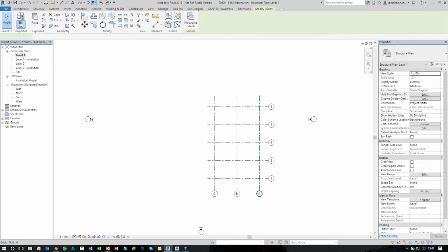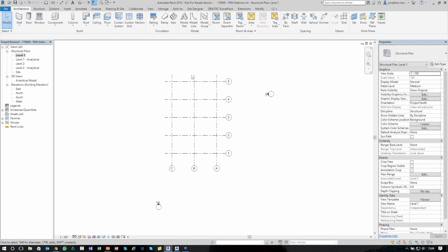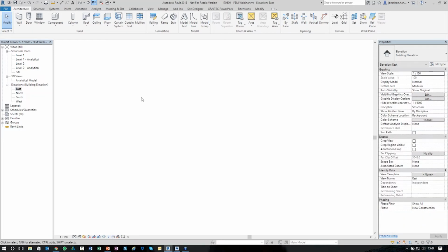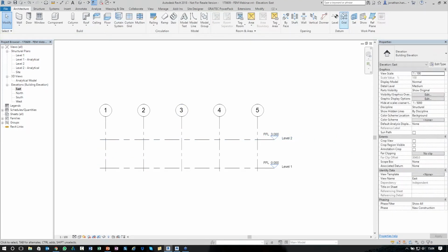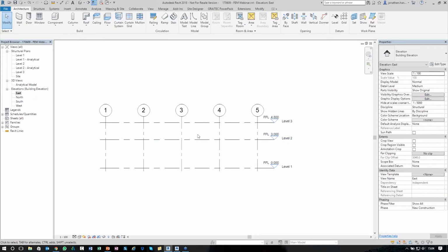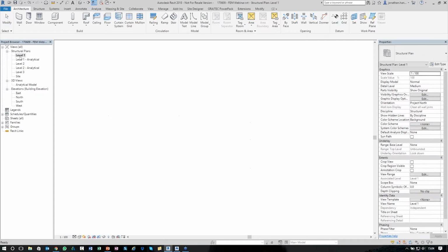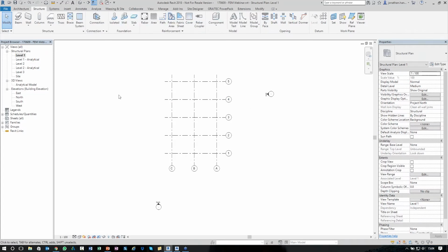I'm going to click into level 1 and start drafting a very simple structural grid. I'm just going to keep it very simple for this process, just to show the connected workflow. I'm going to put in some grid in the X direction, and then some in the Y. As I'm doing that I'm going to switch that to alphabetical, and put 5 meter spacings between them. I'm just going to tidy my grids up a little bit.